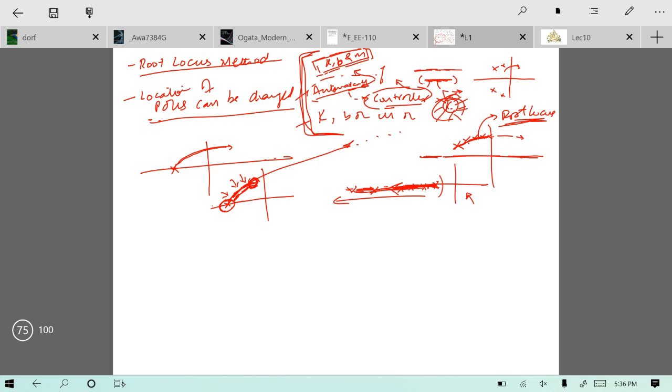So in the first case, the pole path was from this point to minus infinity, so whatever the value of zeta or anything you have, your system will never become unstable. And in the second example, your system was becoming unstable when the root or pole crosses this j omega axis while going along this path to infinity. However, after inserting a 0, it terminated at 0, and the root locus will only be this portion.